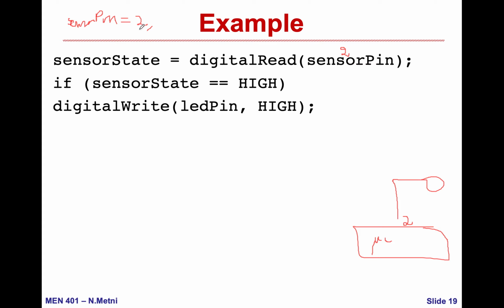If pin 2 is damaged and I want to connect my sensor to pin 7, with hard coding I have to go into the code and replace every 2 with 7. However, with soft coding, I go into the void setup and replace the 2 by 7, and this is it. So it's easier to understand.